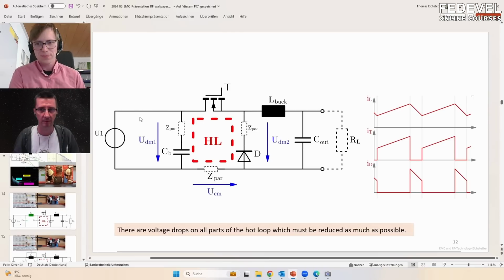So the source of the EMC is actually on this capacitor, the interference source. You will get this voltage drop here, and this is a certain amount of power which is created. It goes in both directions. So it's going in this direction when you look at it from an RF point of view, and also in the other direction, which means a certain amount of energy is now traveling between the upper and the lower line and goes to the source backward.